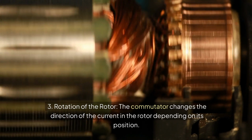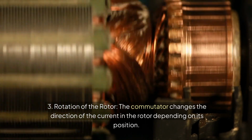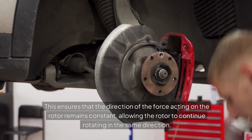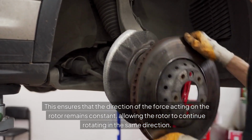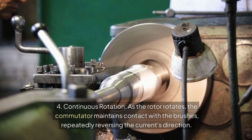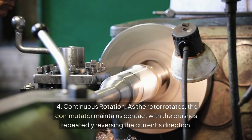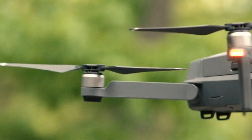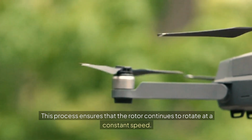3. Rotation of the rotor. The commutator changes the direction of the current in the rotor depending on its position. This ensures that the direction of the force acting on the rotor remains constant, allowing the rotor to continue rotating in the same direction. 4. Continuous rotation. As the rotor rotates, the commutator maintains contact with the brushes, repeatedly reversing the current's direction. This process ensures that the rotor continues to rotate at a constant speed.